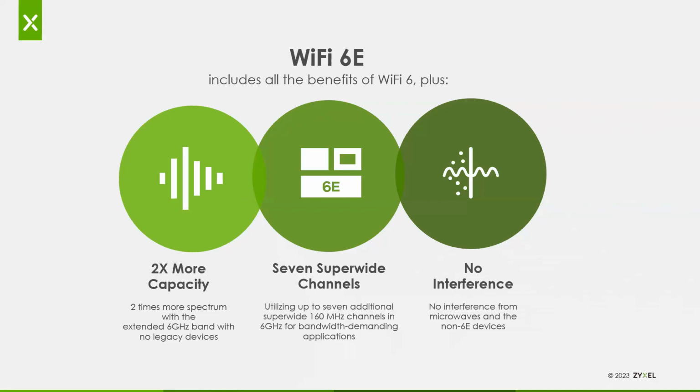And we don't have to worry about interference because basically nothing else is using this except for Wi-Fi. Now there are legacy users, licensed users who had the 6 gigahertz usage for their equipment. It was a lot of utility companies, news reporters, things like that were using 6 gigahertz and continue to use 6 gigahertz as a licensed spectrum, but they are doing it outside. And 6 gigahertz doesn't penetrate walls very well. So you shouldn't have to worry about any sort of bleed in from anything going on outside causing issues for you.